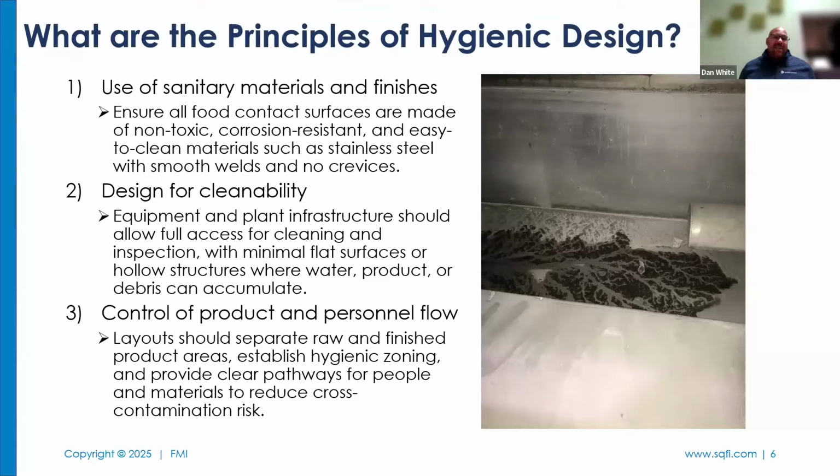I mean, it would be destructive to tear it apart and actually get it the appropriate way, but it just doesn't drain. And that goes to the company did everything right. They sourced an excellent tank from a reputable manufacturer. But they skimped when it came down to the contracting, and they went with somebody local who didn't really have food experience. And so now there's always going to be product residue in the bottom of this. So that goes to you can do most of the steps, but until you do all the steps, you can still have issues. That's what I was going to add.